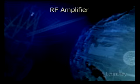As its name would suggest, it is an amplifier for radio frequency, used to increase the amplitude of the signal itself. This positive increase, remember, is called gain, and it's going to be measured in decibels, positive decibels. An amplifier will be used anytime we have to compensate for loss incurred by the RF signal, either due to distance between antennas or the length of cable from a wireless infrastructure device to its antenna.